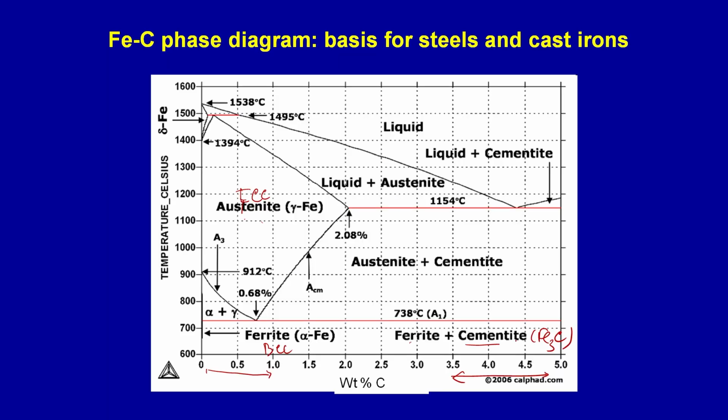like here in the case of iron-carbon, this austenite, which is an FCC solid solution of iron with carbon. So, carbon is a small quantity, but iron is the largest species, the majority species, and carbon is added in a minute quantity. That is why this is a solid solution of carbon in iron. Similarly, alpha also is a solid solution, but it has a very small amount of carbon, about 0.02 weight% of carbon. But cementite is not a solid solution, it is a compound.